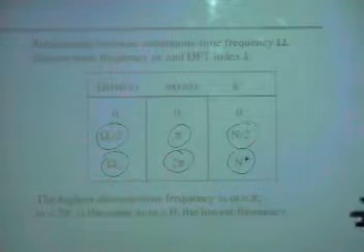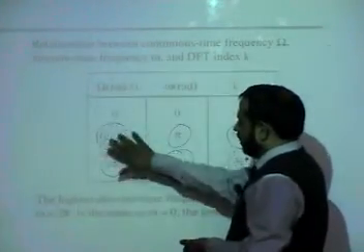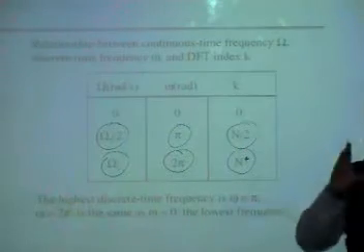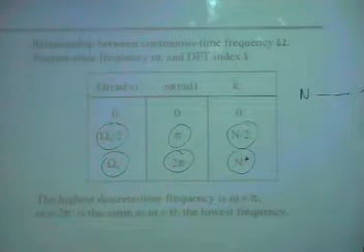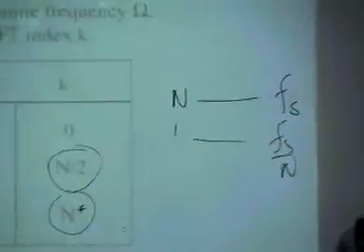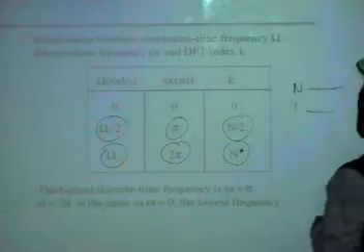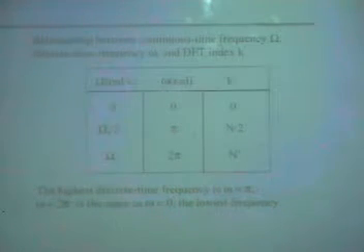Right? So these are the relationships of the frequency axis, analog frequency. Usually we would love to see frequencies in the analog domain because we have a direct correspondence with this frequency. Okay, it's 6 megahertz, 7 megahertz. So once you plot, even in MATLAB, a discrete frequency axis, I've already shown you how to change it. It's a simple change: capital N corresponds to f of s. So one sample corresponds to f of s over N. A simple relationship like this, so you can always switch the axis and label the axis in hertz instead of indices. If you don't do that, MATLAB will label it in indices.